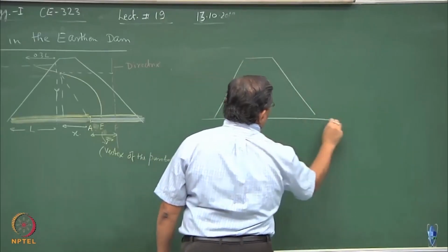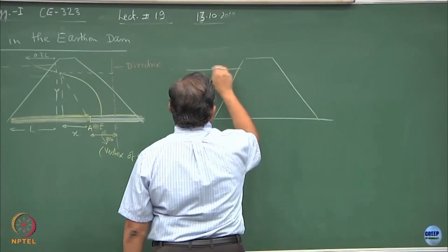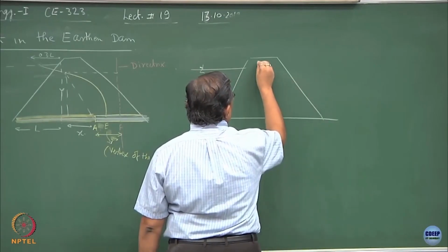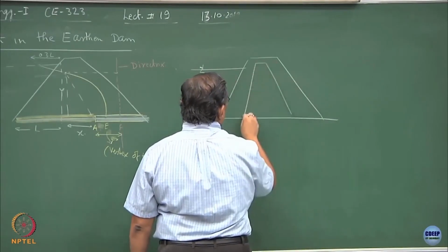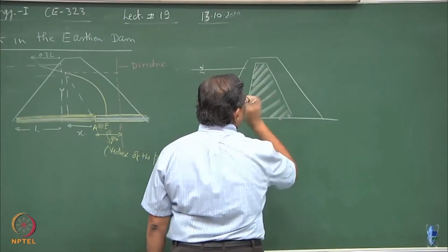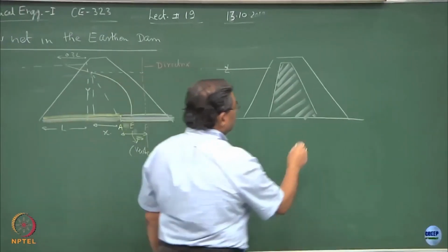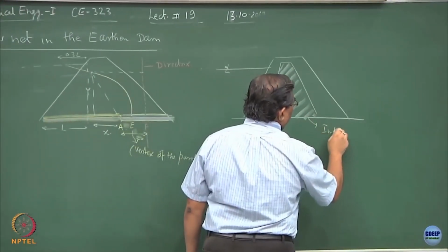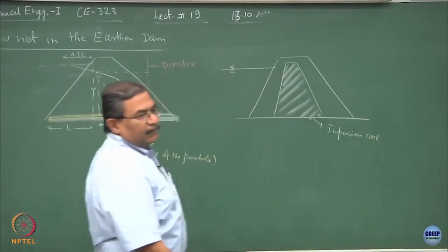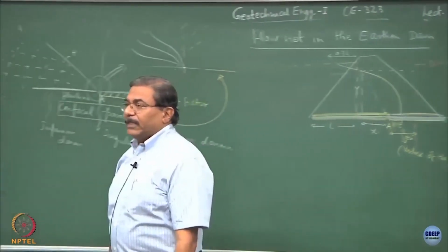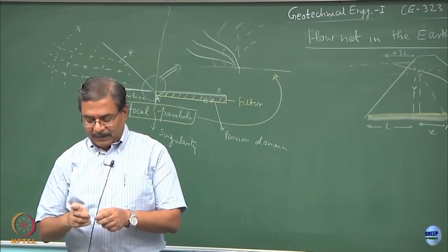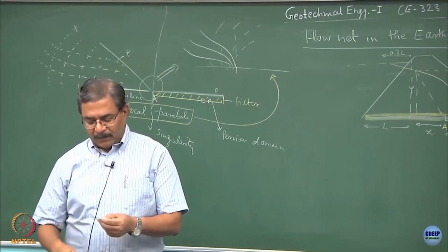material in between. So, suppose this is the upstream water level, and if I want to check the seepage taking place through this, what I have to do is put an impervious core. Now, this becomes the situation which you have already come across in physics when you are dealing with Snell's law in case of light, you know.